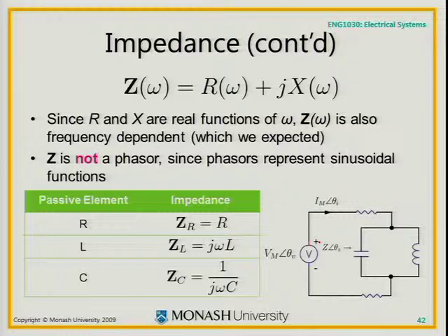We know impedance is frequency dependent. We had jωL, 1 on jωC. You change the frequency, now the impedance changes. And that's what gives us all the flexibility to design all these different circuits to do different things, to respond to certain frequencies in different ways. That's why capacitors and inductors are so useful. So here are the basic impedances of single elements: R, jωL, and 1 on jωC.